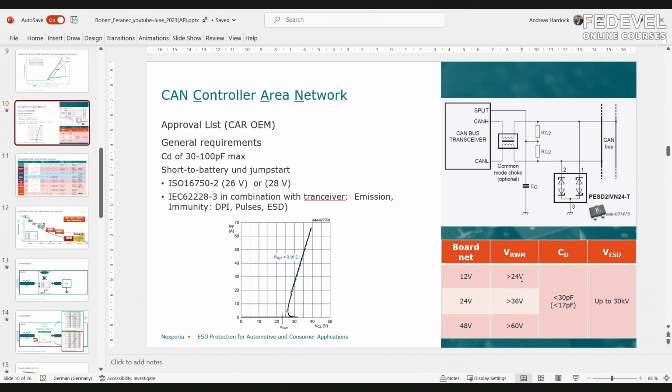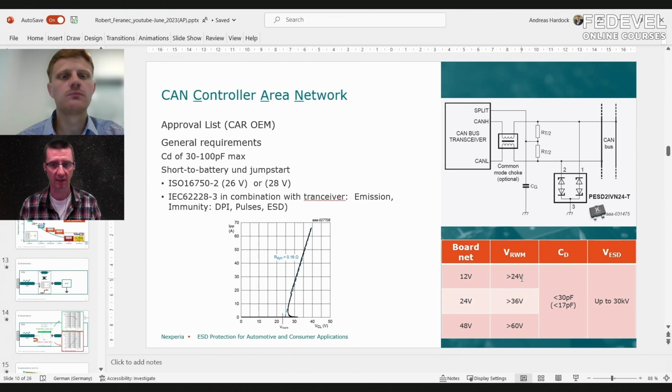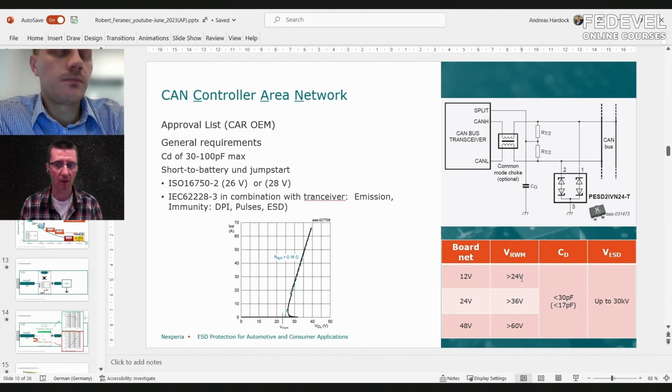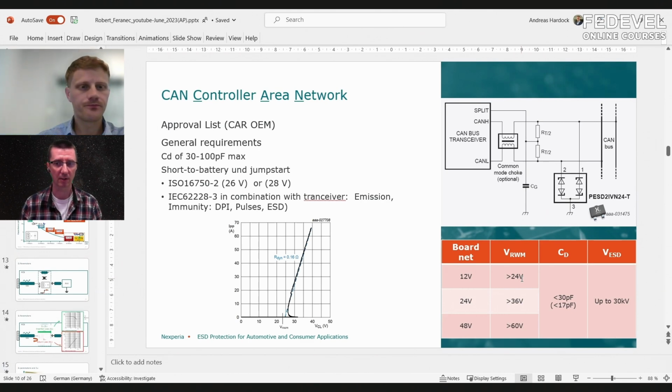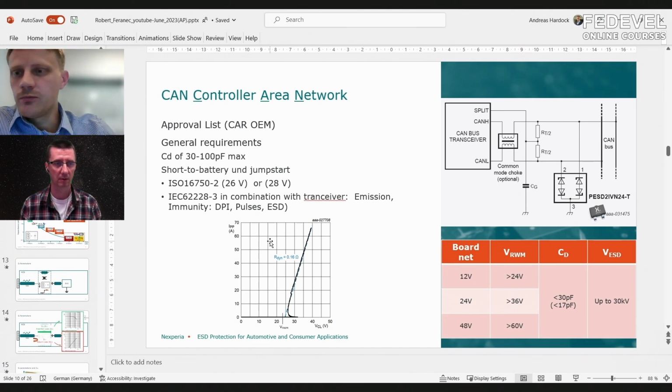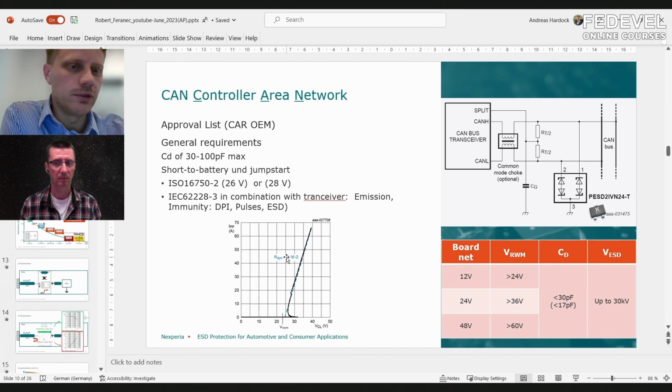But for example, if you work with lower voltage interfaces, which are using signals like 3 volts or 5 volts, then how much space do you need to protect it, or when should this protection actually start working? Usually, for sure above the swing voltage, and you need to look then at the maximum voltage which can be on your I/O data lines. This is different.